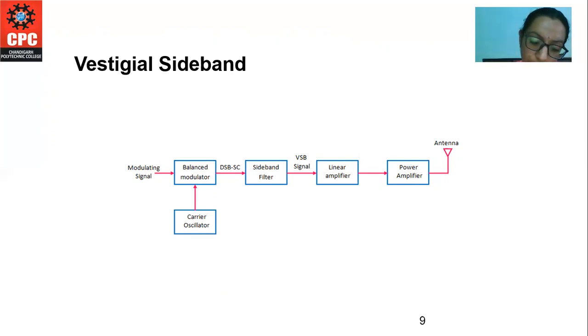So the response of the filter shows our sound sidebands, and a frequency of 1 kilohertz is allowed on each side of the sound carrier. Here the sound is transmitted by FM on a carrier located 4.5 megahertz above the picture carrier. The VSB of the picture carrier is transmitted up to 4 megahertz without attenuation, and thereafter the sideband is attenuated so that it does not interfere with the LSB of the sound carrier. The LSB of the picture carrier is entirely attenuated at 1.25 megahertz.